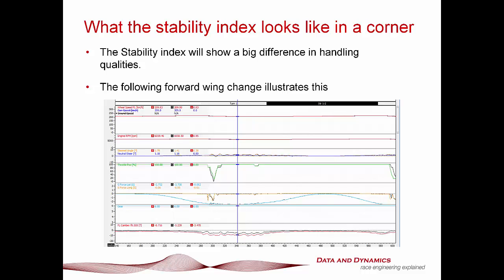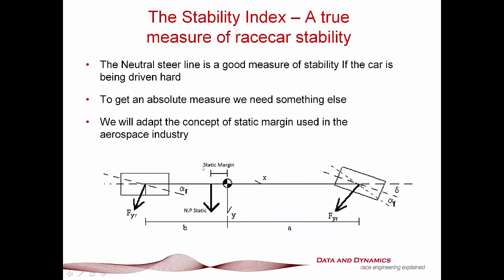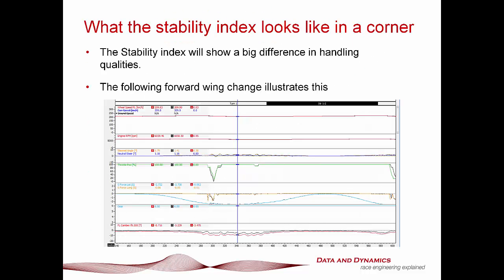In a lot of cases, particularly if your driver is good, they're not so much commenting on a huge change in grip or a huge change in the variation of steer angle. What they have felt is this static margin actually reducing. So that's something to keep in the back of your mind when you engineer a car.